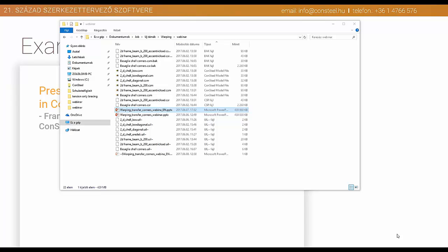Now if I switch it back on, then visibly the different types of connections are shown. First, I need to select the model portion which I want to use as a pre-selection of my corner definition, and then I select the type of connection which I want to apply and push apply. When I push apply, you can see that now I got two yellow buttons. If I push the other one, which is for the diagonal, then I will get green boxes. If I select the red one, which is for box diagonal, then it will be red.